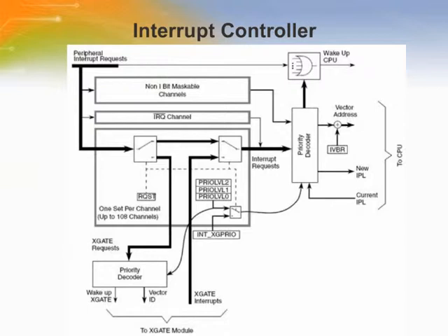The interrupt controller module for the S12XE allows up to 7 levels of interrupts to be available to the user. The XIRQ, SWI, BDM, unimplemented opcode, and system reset interrupts are available. Each interrupt source can be allocated one of 7 possible interrupt levels.